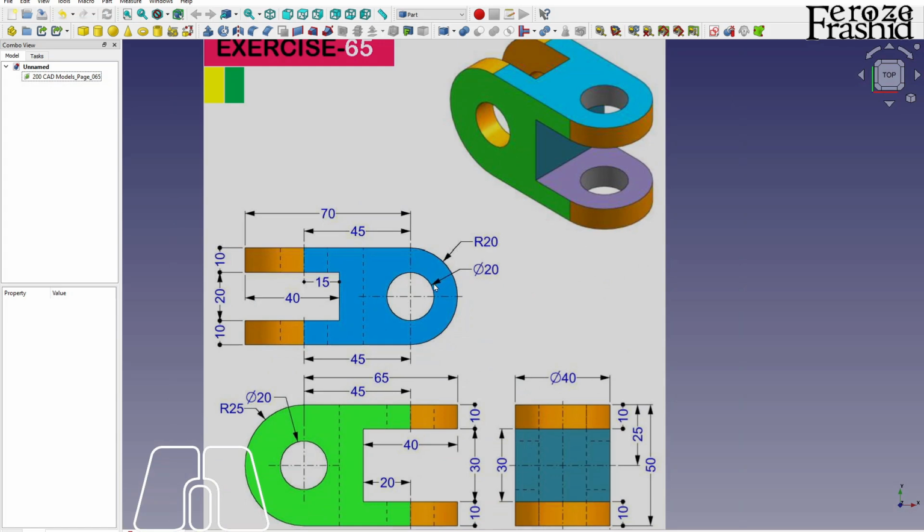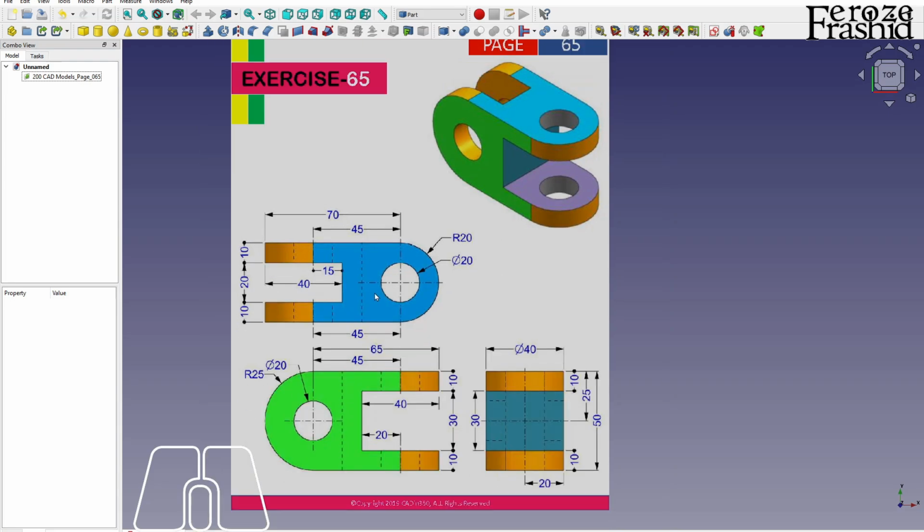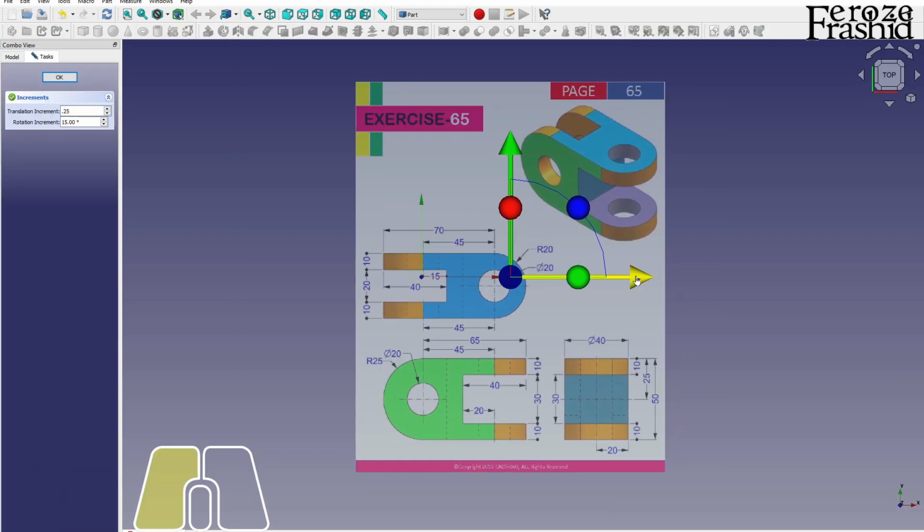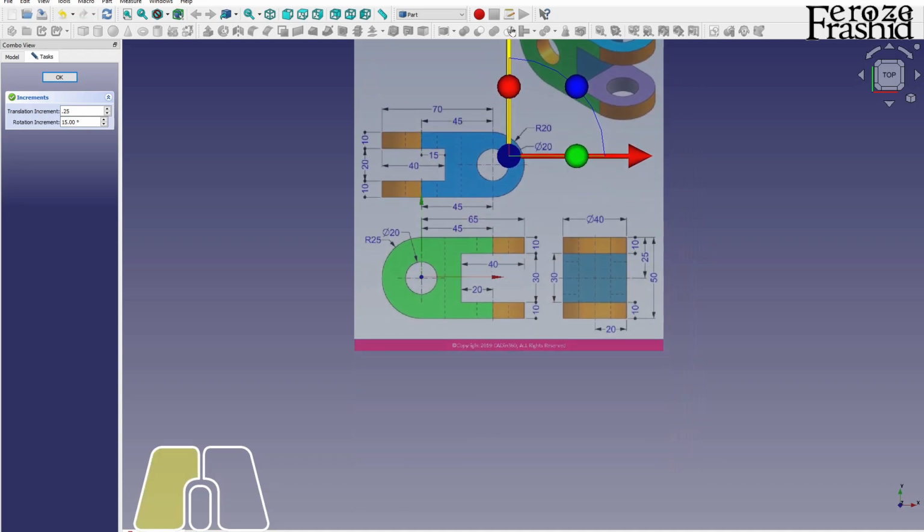So this hole is diameter 20 and the outer periphery is radius 20, whereas on the other side, this outer periphery is 25, so that throws off the symmetry from our calculation. For that reason, we will have to build the whole object, and otherwise I would use one sketch to manipulate the entire object. If I have time by the end of this video, I'll probably show that one, but for now let's go ahead and relocate the center.